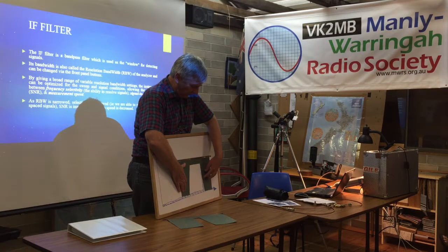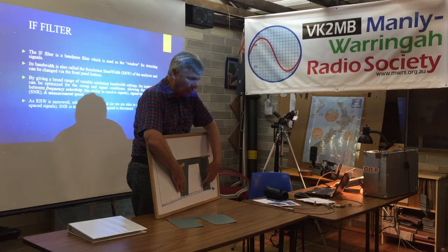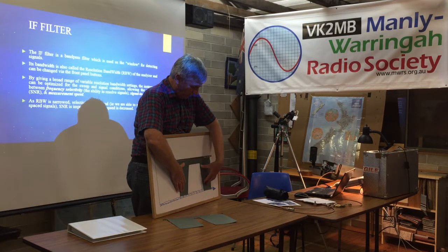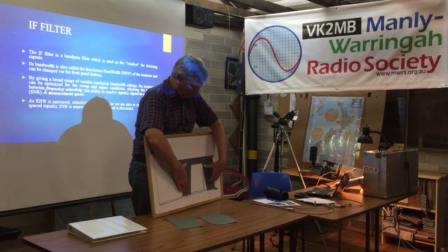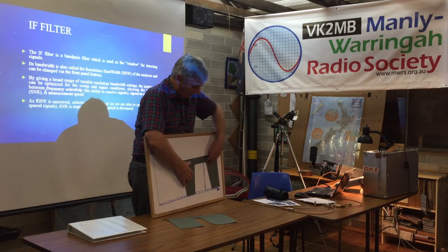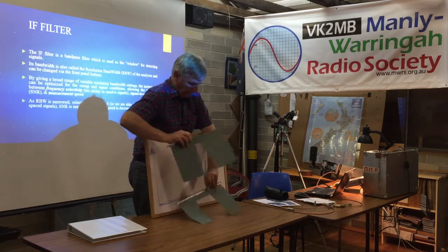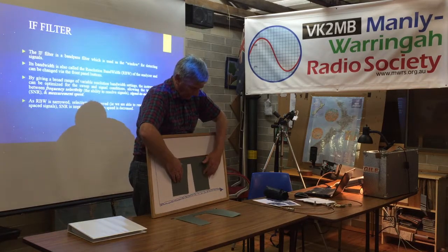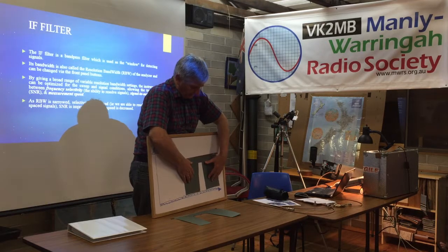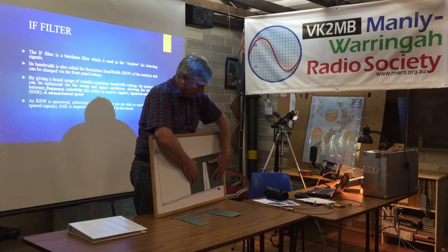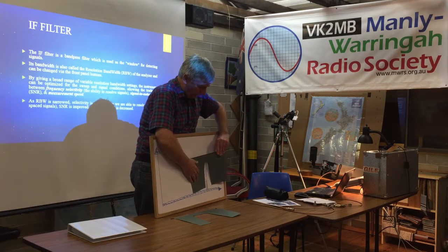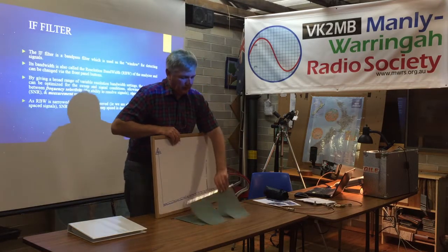All this is effectively noise. So with a wide filter, you get a lot of noise as the thing sweeps along until you finally get it within the centre there. As opposed to a narrower filter, as it sweeps along, there's a lot less noise as it gets into it, and then it sweeps and it's gone out the other side.